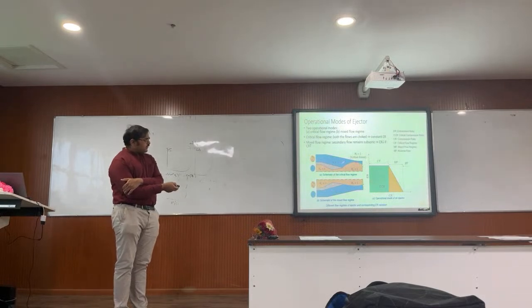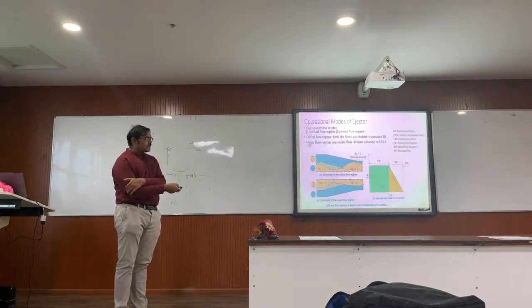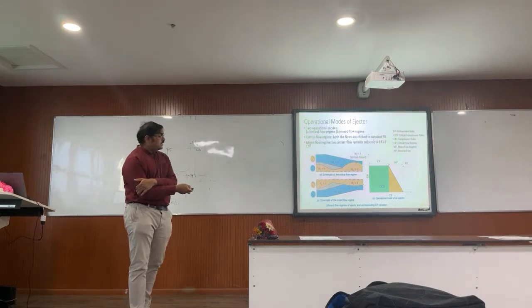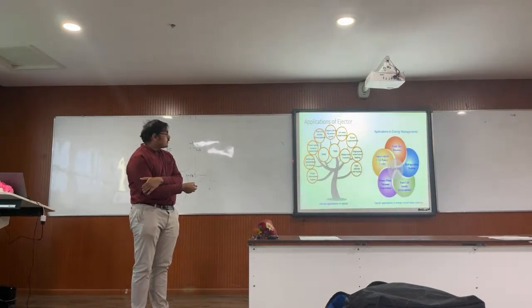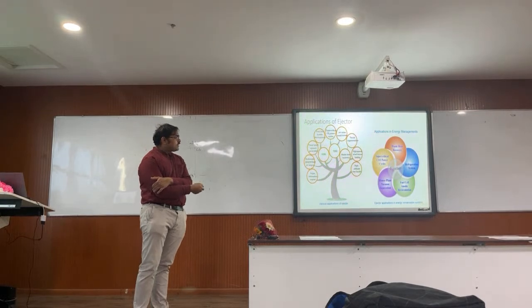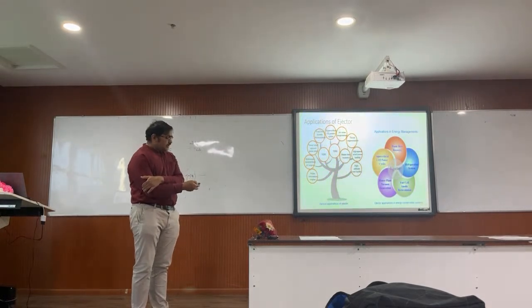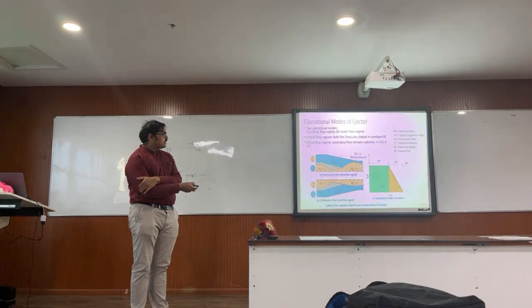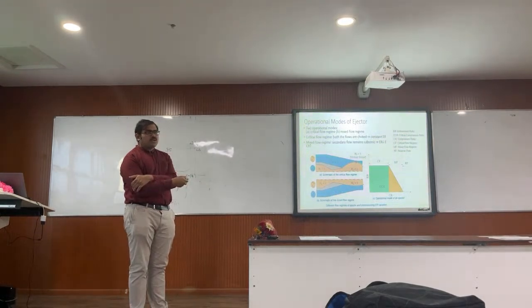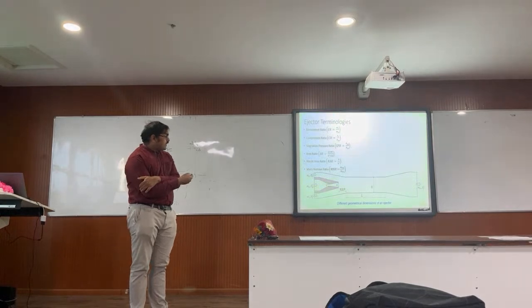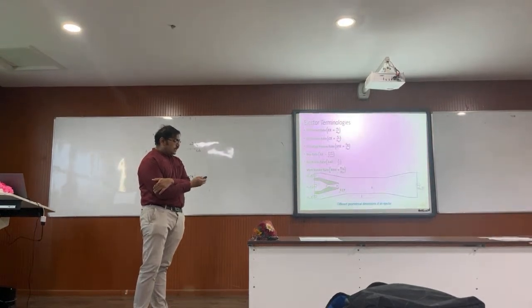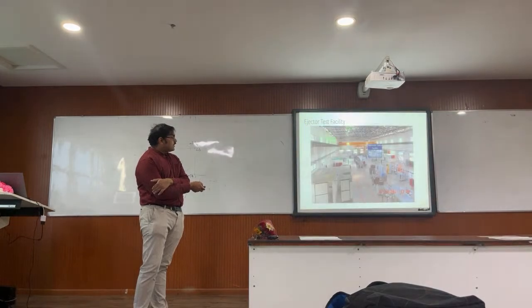So the maximum mass flow rate of the ejector is obtained in the critical flow regime, and in many applications, particularly when we look at something like anodic recirculation, energy-based applications for refrigeration systems, supercritical CO2 power cycles, these kinds of energy applications of ejector need the ejector to work in the critical zone, in this particular zone where the mass flow doesn't change. So we have carried out experiments in our laboratory to look at these.